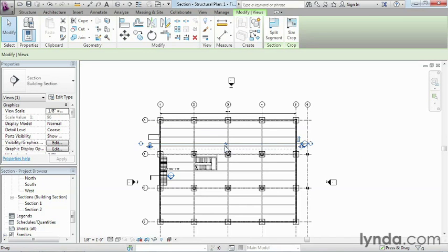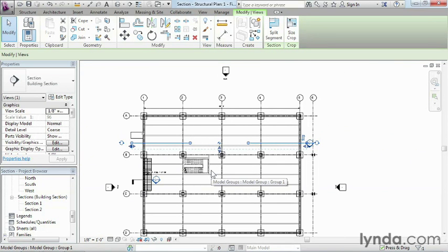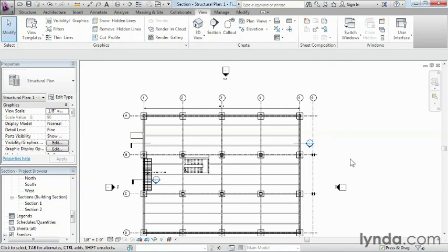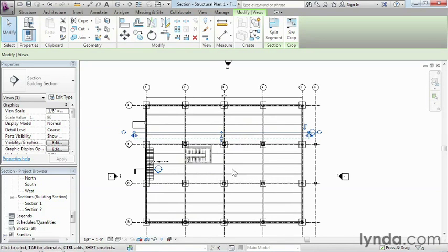If we go ahead and zoom in here and click on this little break tool, what it actually does is it splits this line into two pieces. It doesn't affect how the section actually works, but I know that some people like to see this symbology where they only see a part of this line going through their drawings. So you can absolutely create that condition just by clicking on the section symbol. Also, if I click back on the section symbol again and then click back on that little break, it'll automatically heal itself again.